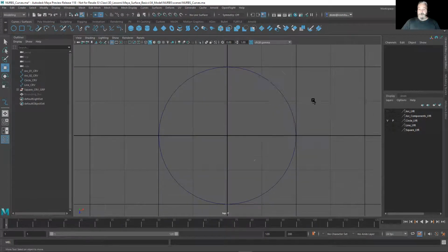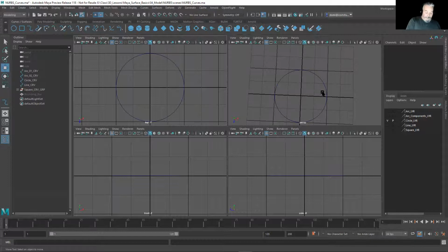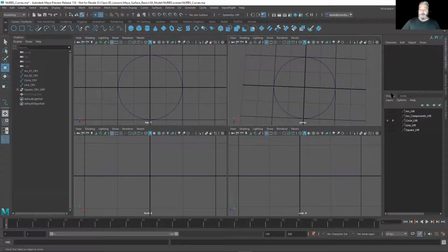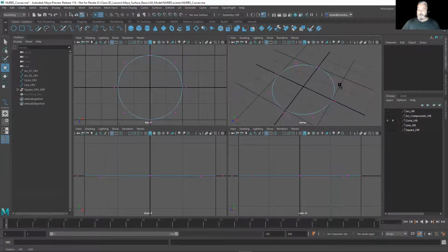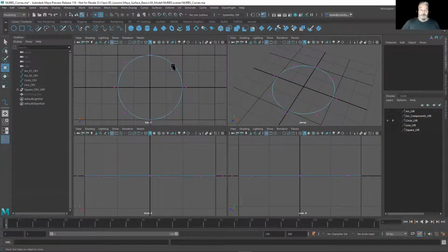And they're very helpful. You can do Shift F, circle. Okay. So there's a circle in there, and I actually have the edit points displayed on this one here. Let me switch it off and I'll show you how to do that. That would be this tool here.